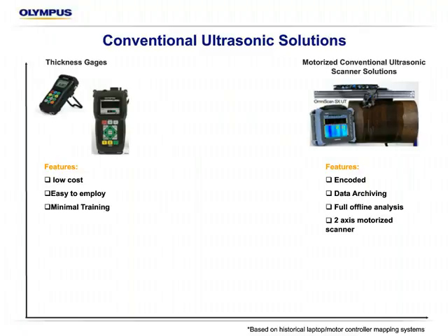Typically the conventional ultrasonic methods for detecting corrosion are on one of two tiers. On the low end, we do point measurement or data logging with thickness gauges. That's an ultrasonic sensor with either a numeric readout or a waveform readout of the energy along with a reading. These measure the thickness only at the point where the sensor is located. A lot of good features for these, and it's obviously the easiest and most inexpensive way to measure corrosion. It doesn't take a lot of training, and is very easy to use.